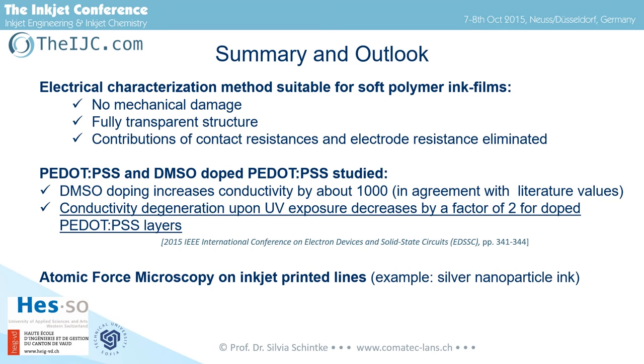And with doping of the PEDOT:PSS, we have succeeded not only, as already known, to improve the conductivity, but we have also found out that the UV stability improves by about a factor of 2. And our main issue now is to study, in general, inkjet printed structures with atomic force microscopy to know more about the nano and microstructure in such inkjet printed electrodes.